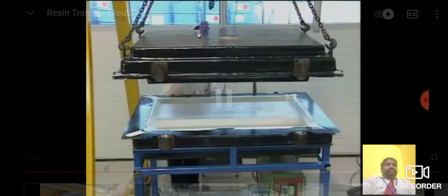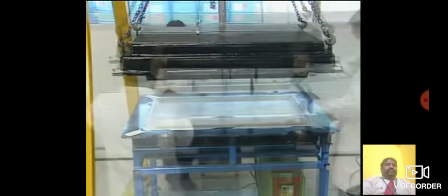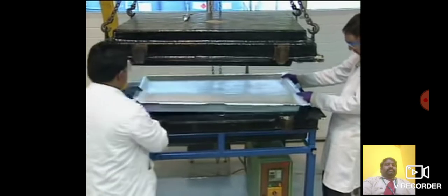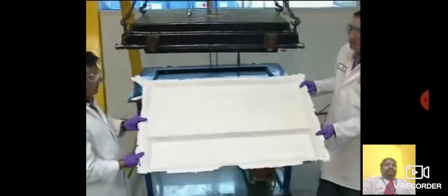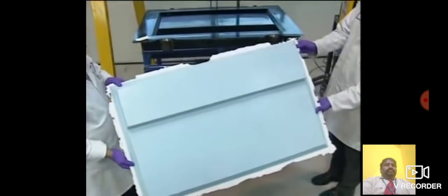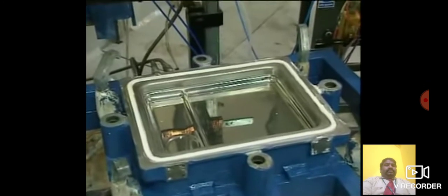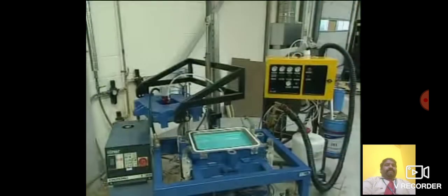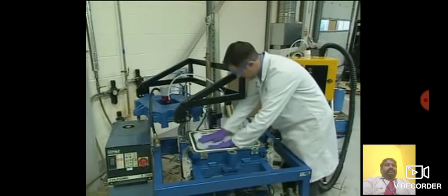Once the resin has cured, the mold is opened and lifted to allow demolding. The heated tooling allows quicker curing of the resin, and so quicker cycle times are achievable when compared with ambient temperature processes. RTM can use metal molds such as nickel shell, aluminium, or steel for maximum durability and improved surface finish. However, the principles of the mold design and the process remain the same.